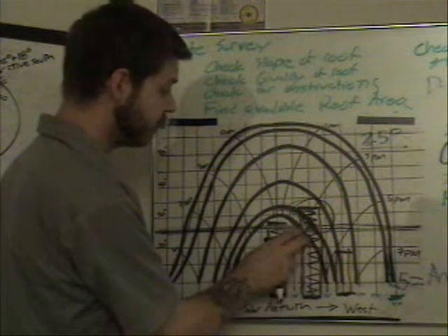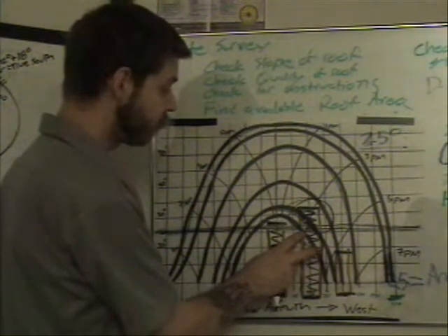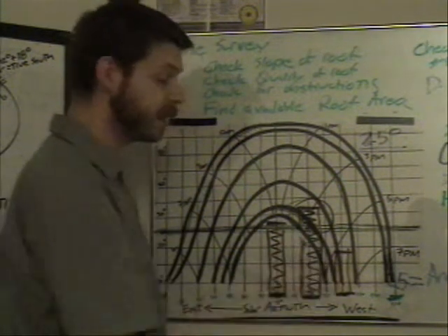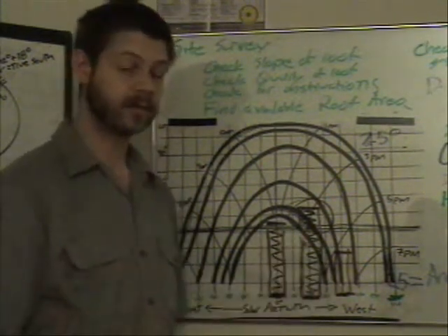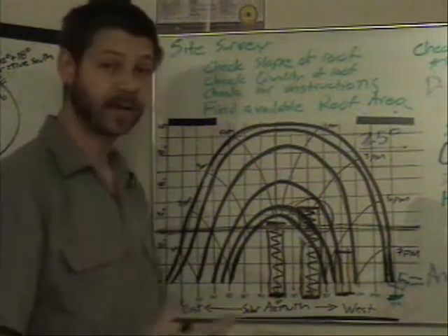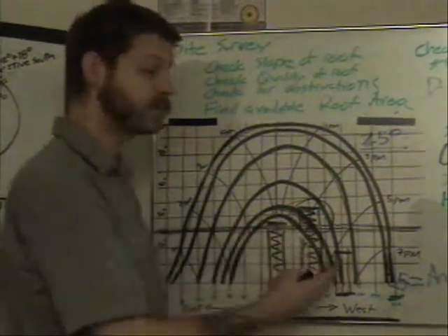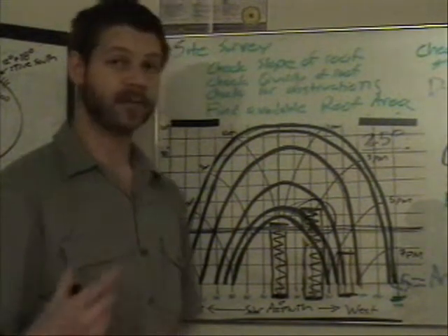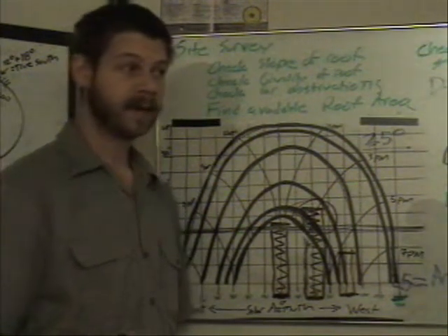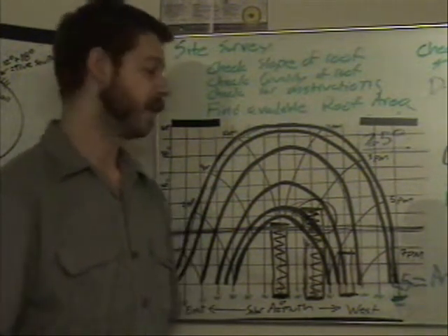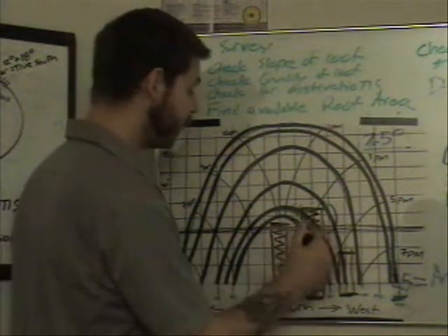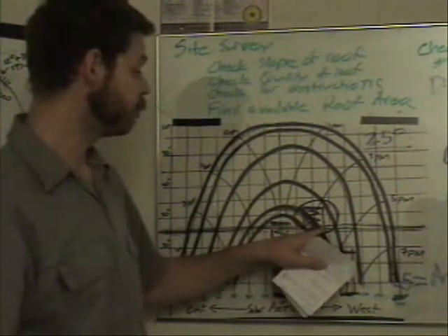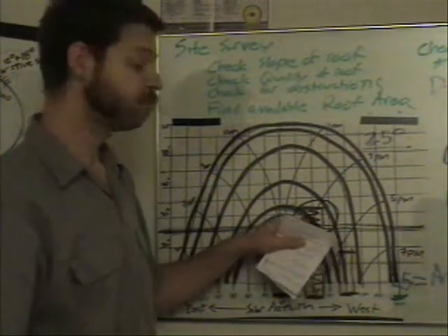And then as it drops down, it'll also cause shading from 3 p.m. to 5 p.m. But because what we call the solar window, the peak sun hours of any location, are between 9 a.m. and 3 p.m. solar time, that isn't going to affect the production of the system in a significant way, in a way that will affect our calculations. This portion right here will cause a significant drop in those months because it cuts